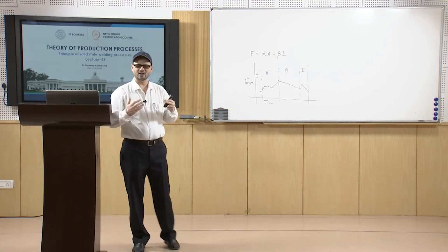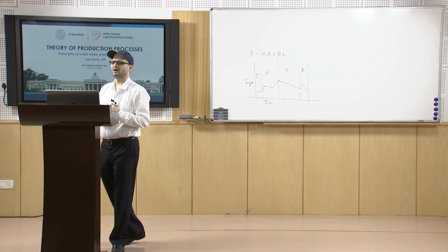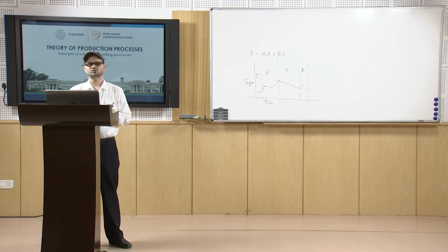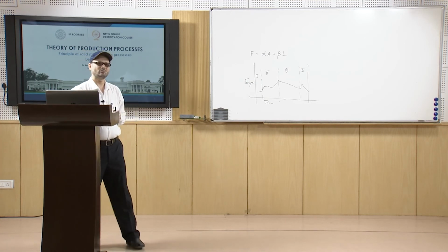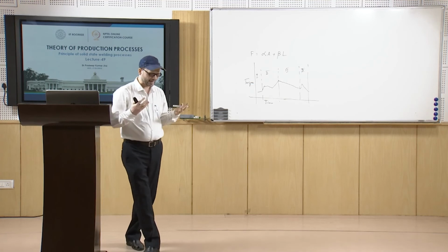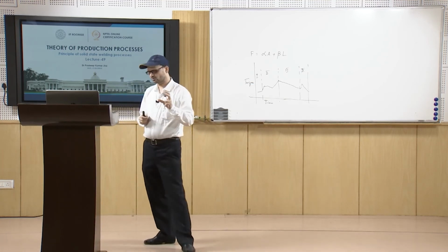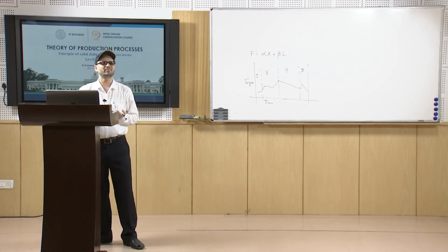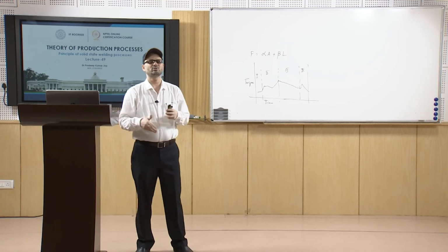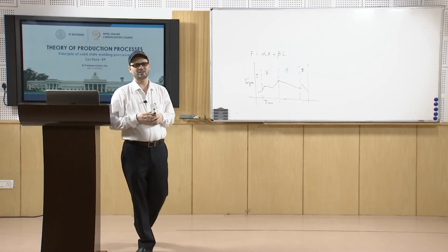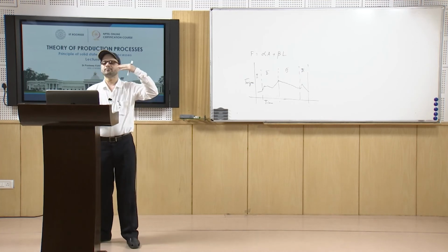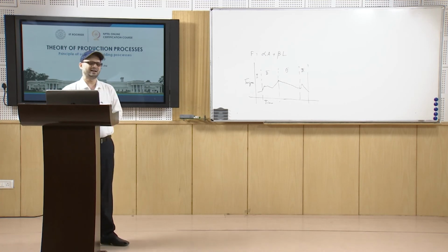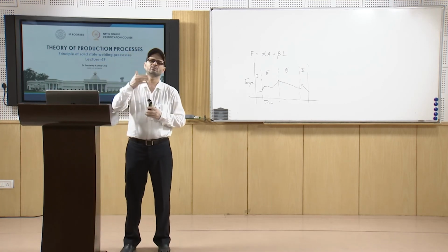As you know, the inertia of the flywheel can be used for finding the energy. That will be half I omega square, where I is m into k square, with m the mass of the flywheel and k the radius of gyration. Based on that you can find I, and omega will be based on the number of rotations, 2 pi n by 60, if n is the RPM. Based on that you can find the energy associated with such processes, and the velocity is also one of the factors.